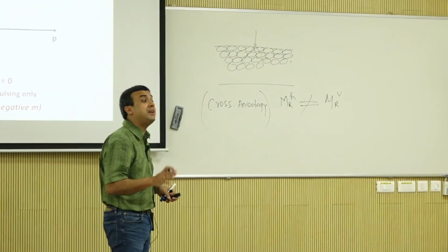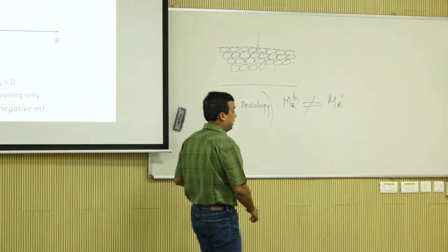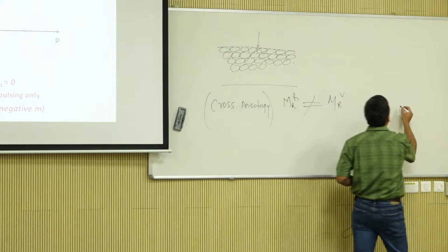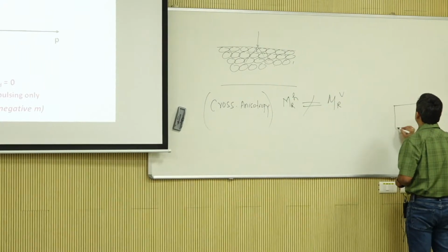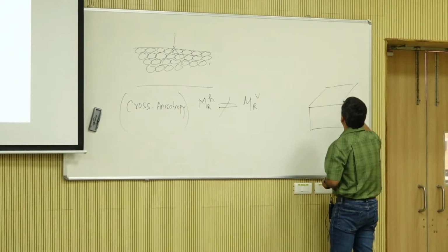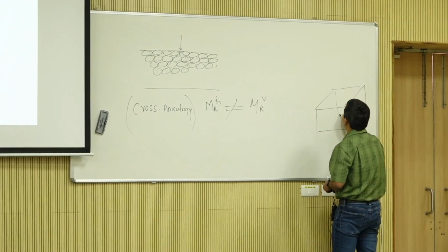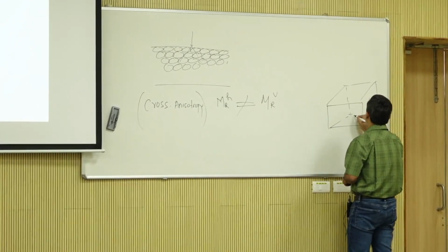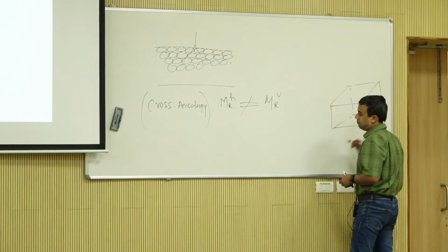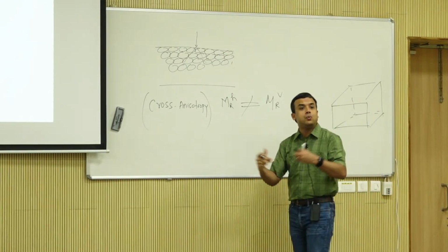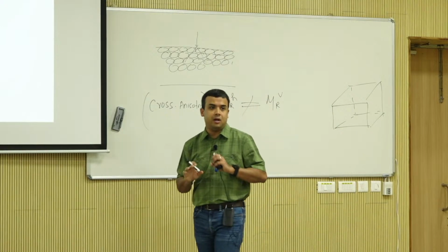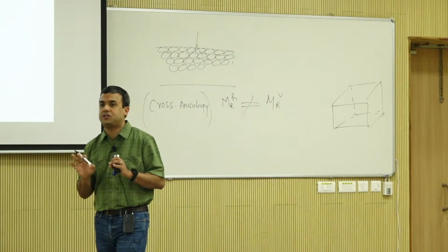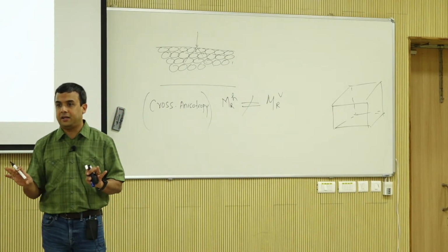Now, if you had a true triaxial setup, where you actually had the ability to control all the walls, you would be able to test whether 2 and 3 are also different or not. But we're not talking about that right now. We're still talking about cylindrical triaxial, right?